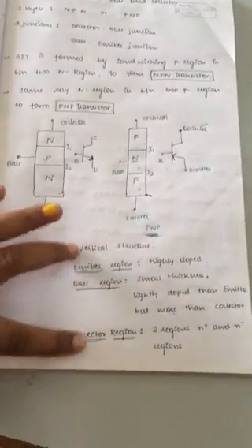Coming to the thickness of the n minus layer, the thickness of an n minus layer determines the breakdown voltage capability of the transistor. The n plus region again is highly doped. The n plus region serves as a collector contact for the external circuit, meaning it is connected to a terminal part. Let's understand the diagram, then we can understand how the doping has been done here.